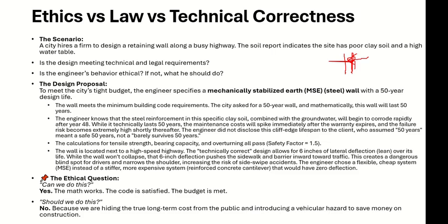Okay, but you know that because of the site conditions, it will not last for the full 50 years. Within 48 years it will start, or it will fail. Okay, if you want to extend it to 50 years, then you have to do extra maintenance. You may have to replace the corroded part, or the part of the steel which is damaged. Okay, so the calculation says it will last for 50 years, but to last for 50 years it needs extra maintenance cost.